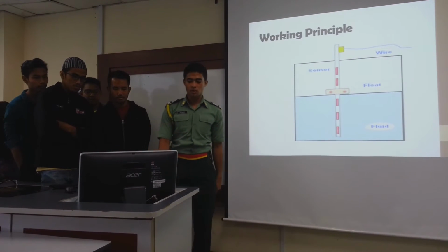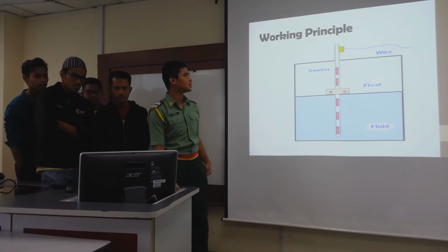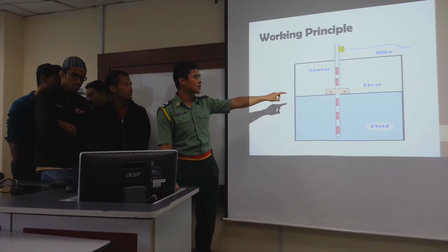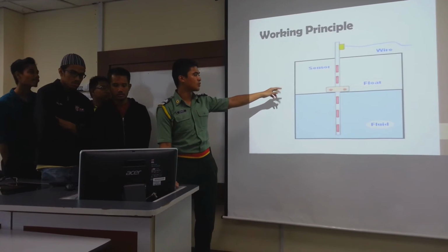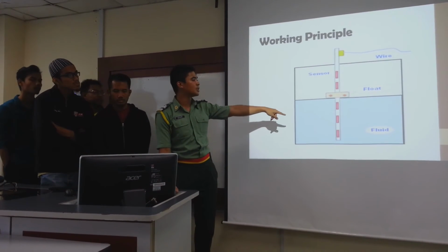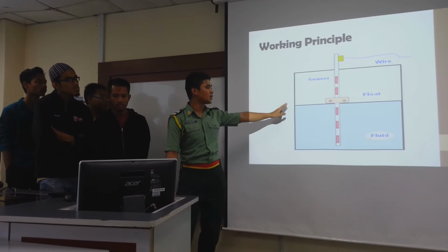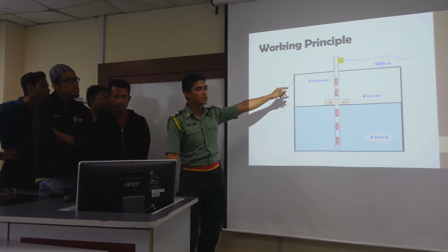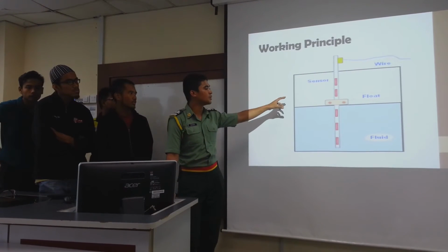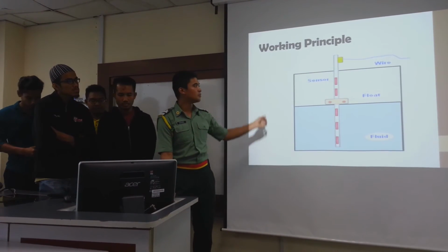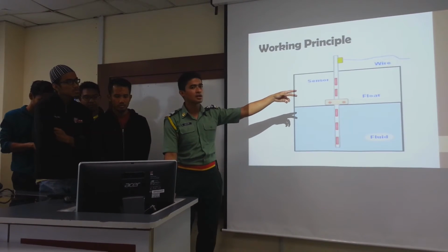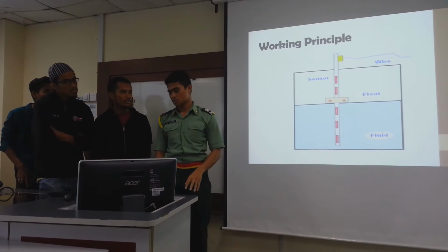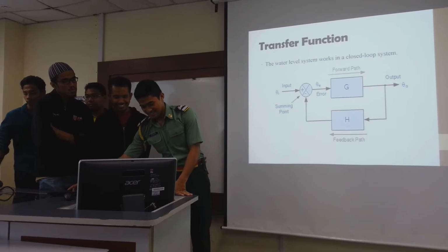Right. For the working principle, this is the working principle of the sensor. As you can see, the floating element will rise up along with the fluid, which means when the fluid level increases, the float will rise up, and the sensor will detect the displacement of the fluid that increased. Then it will be transferred into an electrical signal to the monitor.